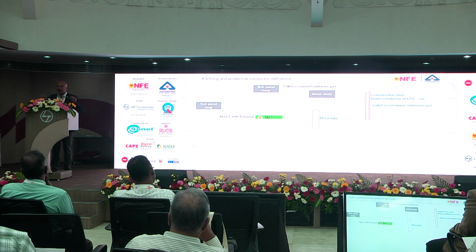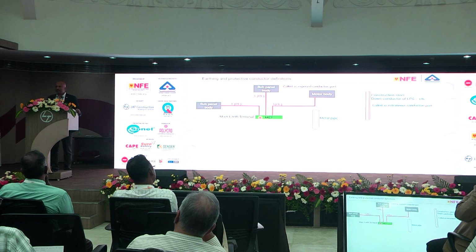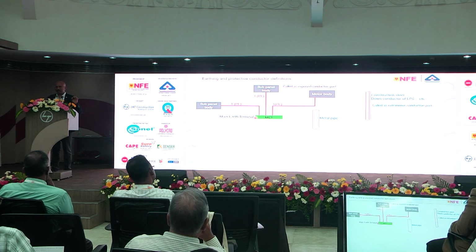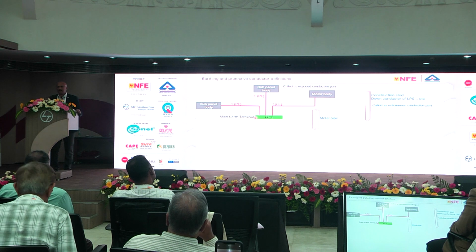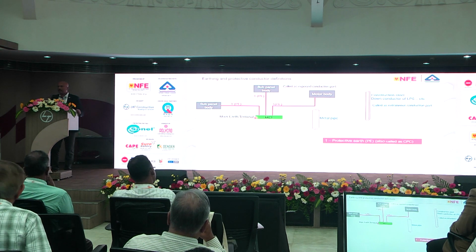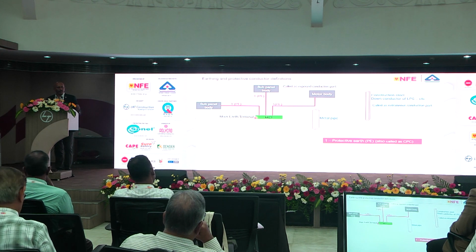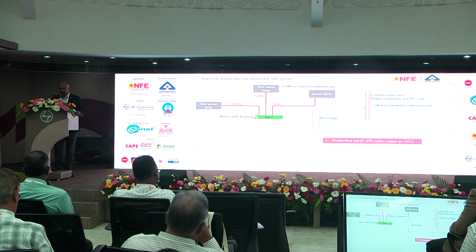That means you have to have one bus bar. Now, all your exposed conductive parts must be connected to the MET. This is called protective earthing, and this conductor is called the protective earthing conductor. Sometimes, from the last distribution board to the socket, these wires are also called CPC, circuit protective conductor. Basically, this is called the protective earthing conductor.